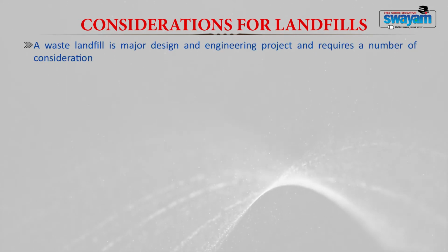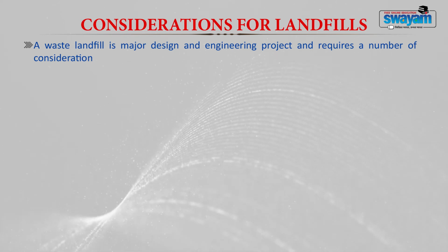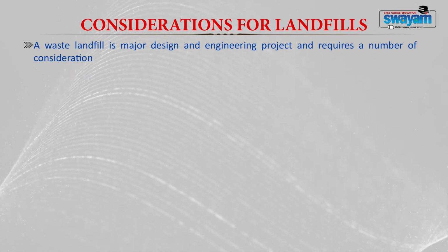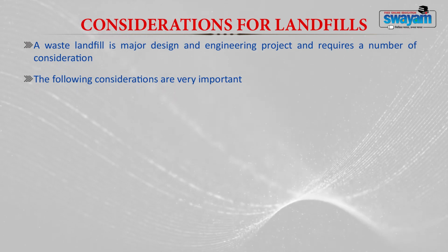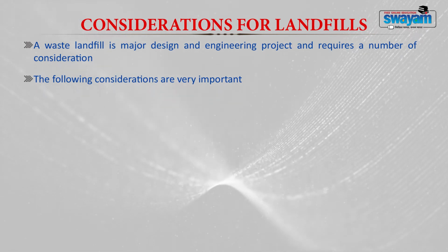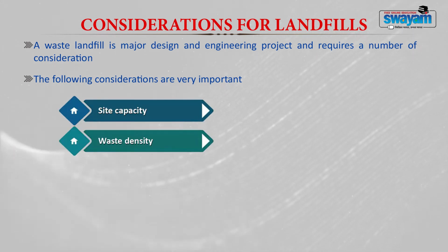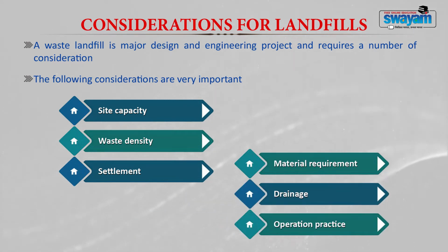Now, what are the considerations for landfills? As I told you earlier, a waste landfill is a major design and engineering project, and hence you have to look into a lot of considerations when you engineer a landfill structure. So, what are those considerations? We will discuss them in detail. The important considerations which you have to look into while engineering a landfill are: 1. Site capacity, 2. Waste density, 3. Settlement, 4. Material requirement, 5. Drainage and 6. Operational practice. Now, we will discuss each of them in detail.